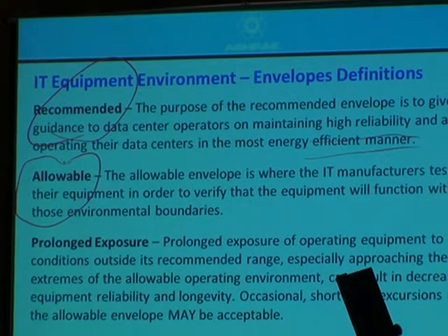And we usually put them in what we call elevation chambers. So they're chambers in which we can take the equipment up to like 3,000 meters in altitude, and we can change the temperature and the relative humidity over many extremes. So it's a much bigger envelope, and we say that envelope is where our equipment operates. It will perform there. It just may not perform reliably for long periods of time if you stay in that larger envelope.